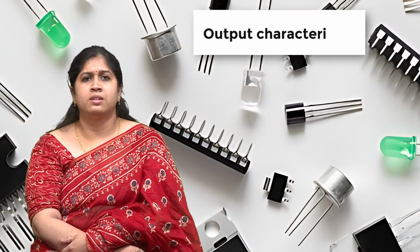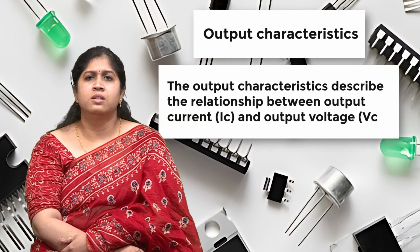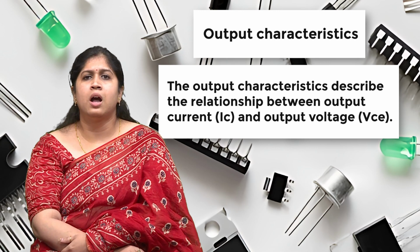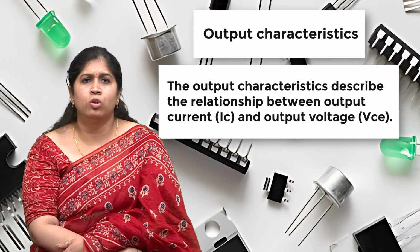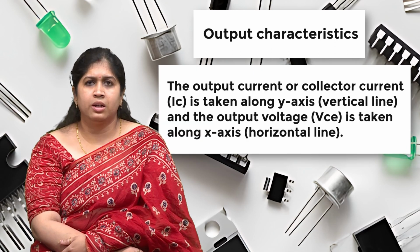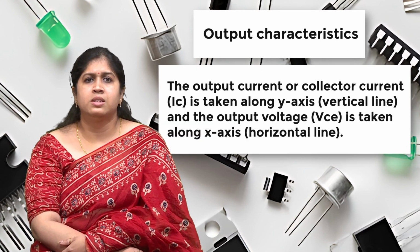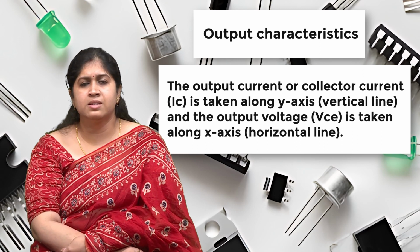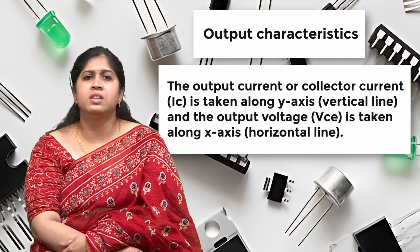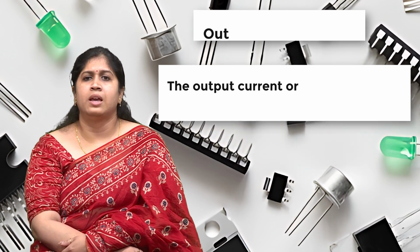Now, output characteristics. The output characteristics describe the relationship between output current IC and output voltage VCE. The output current or collector current IC is taken along the y axis, the vertical line, and the output voltage VCE is taken along the x axis, the horizontal line.